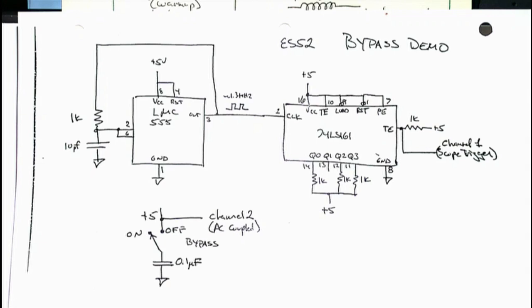And the outputs of that are either sinking current. These outputs at the bottom are either 0 or 5 volts. So either 0 or 5 milliamps is flowing through these resistors. So I got 3 resistors. Anywhere between 0 and 15 milliamps is going on and off, on and off. 15 milliamps isn't a lot. But this is being supplied by a 5-volt supply over here through some wires.